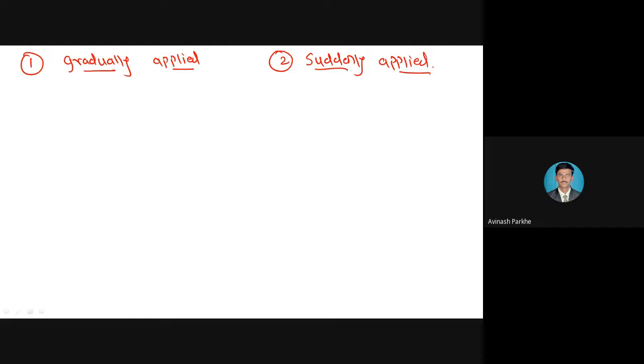Yes, stress due to gradually applied load. Sigma is equal to P upon A. Yes, 70.73 Newton per mm square. Delta L is equal to sigma L upon E. What will be the deformation?